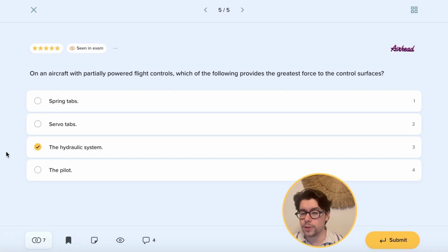So in this case, the pilots will feel some of the aerodynamic feedback on the controls, as they do need to overcome some of these forces themselves. And also these will be reversible because you have the feedback on the controls from the control surfaces. And as you move the control surface, also the yoke will move in the cockpit.